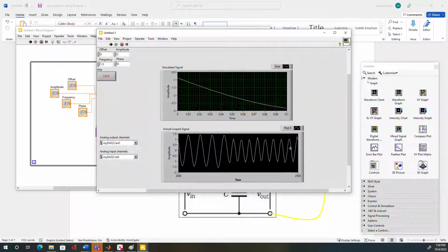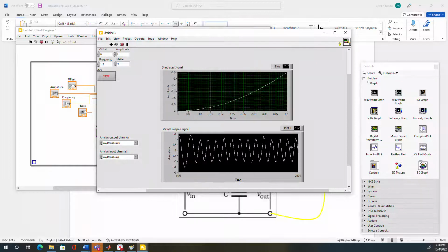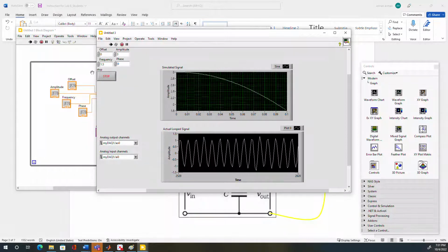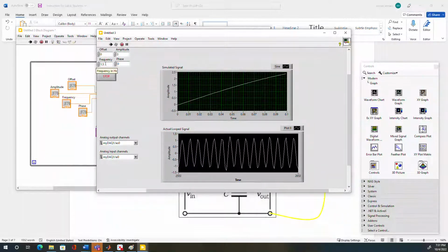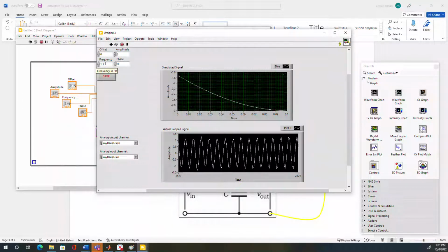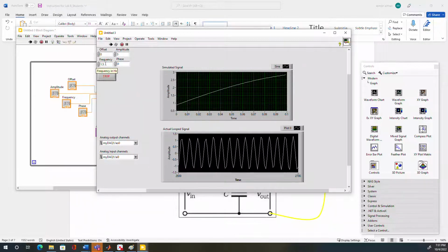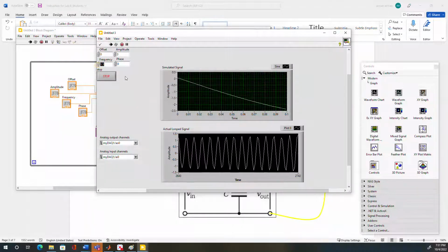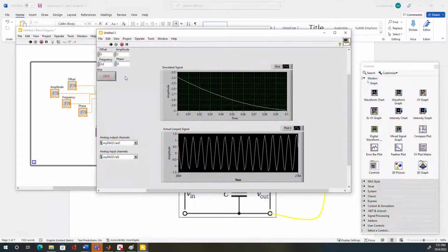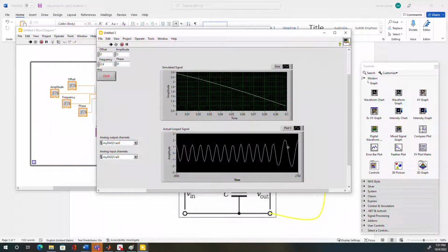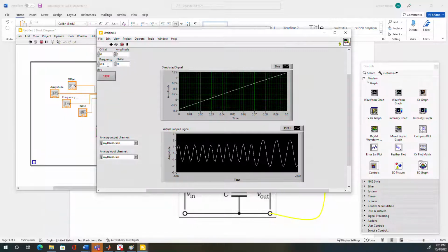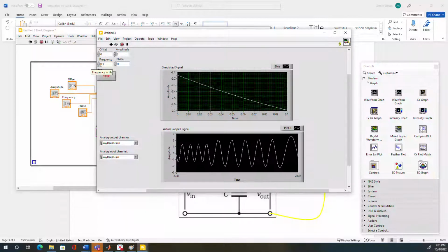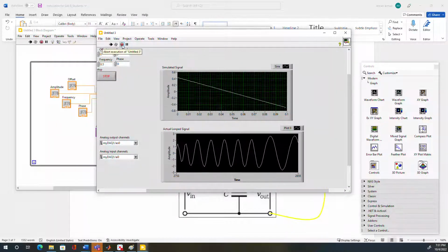You may notice that the signal is not a really great sinusoid. It's because the sampling rate is not set for higher frequency. Another great thing about the RC filter is that when you add noise, which is high frequency, it is going to get rid of the noise. Let's say I set this at 0.9 hertz, which is not much attenuation. There is still attenuation, but not that much. Let's put it at 0.5 so that you can see it better. And then I'm going to stop this.